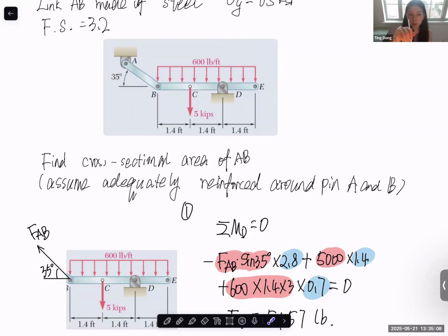That fastener hole may increase the stress level to 3 times the normal stress generated here. So in a real situation, it may fail here and here first before it fails here.